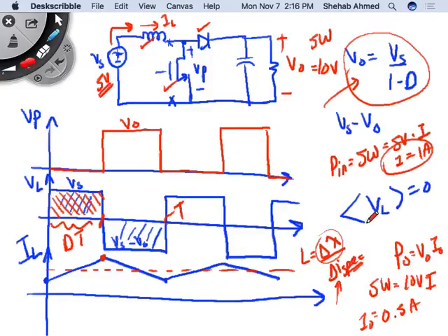This peak current, Imax, is equal to the average value of inductor current plus delta I over 2. Delta I is a spec. The average value of inductor current you have from the power that you're trying to deliver. You're trying to deliver a certain amount of power, so you can calculate the average value of inductor current. So it's easy to do this, right? You can go in and estimate the parameters for your various components in the circuit. So now we've selected L.